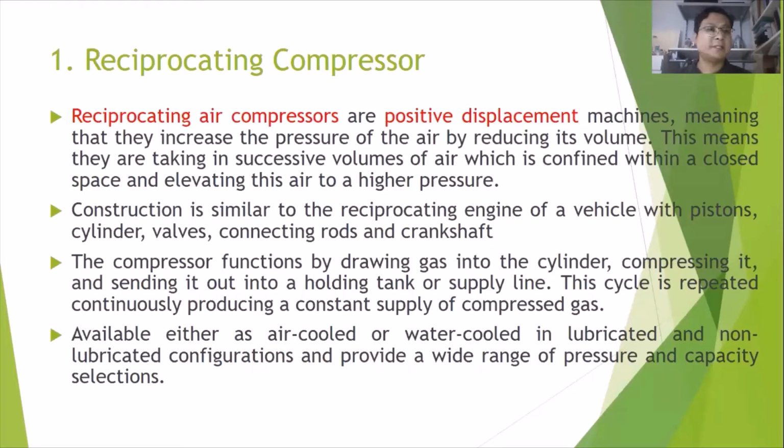This means they are taking in successive volumes of air, which is confined within a closed space, and elevating this air to higher pressure. So we change the pressure from this condition. Actually, from the differential pressure, the fluid will flow automatically.